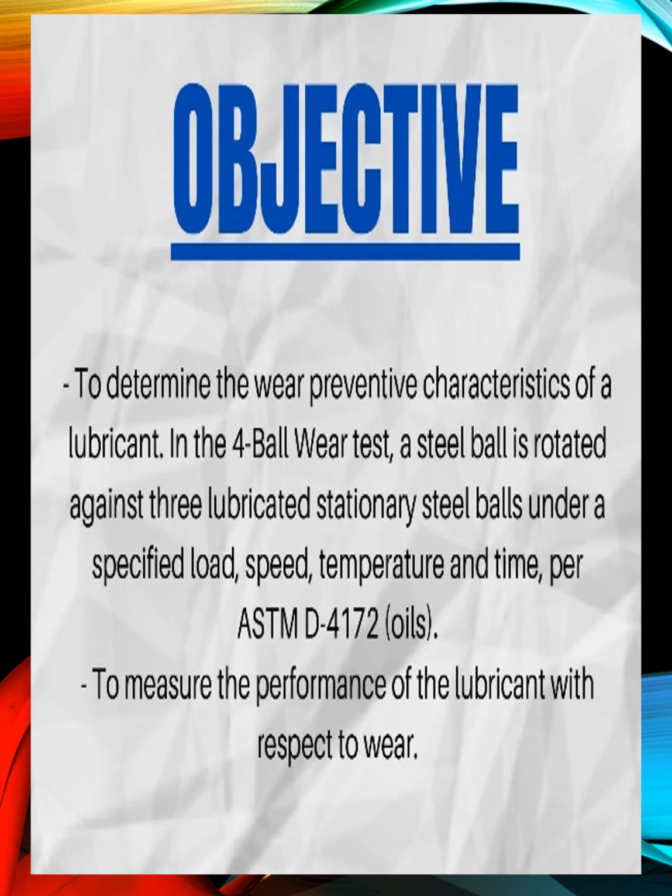The better the lubricant is at preventing wear, the smaller the wear scar will be on the three stationary balls. At the conclusion of the test, the three wear scars are measured and the average is reported. The coefficient of friction is also measured throughout the 60-minute test, with the average being reported at the end of the test. That's all for me.